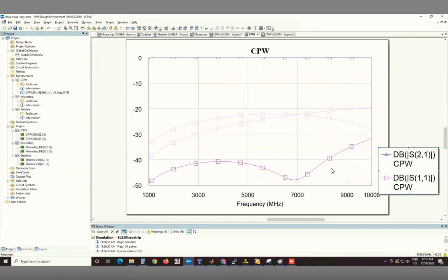Now at minus 40%. So those things do make a difference. And typically what you will see is that if you don't do this in a real structure over a very long period, you'll actually get a resonance. At some point, you'll get reflection because your CPW mode and your slot line mode, energy starts to flow between them. And on the other end, if you have a slot line mode that is not terminated in 50 ohms, because the two slot line modes are just shorted to each other, that creates a boundary condition which then leads to a resonance.